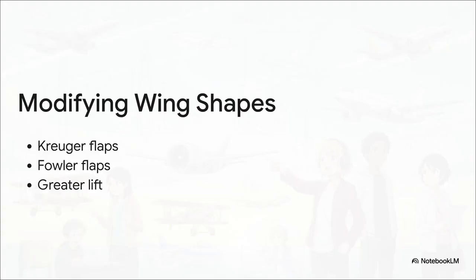So, how exactly do heavy, high-speed jets manage to land safely at slow speeds? Well, advancements in engineering solved this. High-speed jets use leading-edge Kruger flaps and trailing-edge Fowler flaps. When these flaps are extended out from the basic streamlined wing structure, they literally modify the basic wing into that highly efficient, classic concave form. This generates the massive amount of lift required for slow flight conditions, like takeoff and landing. It's honestly a real game changer.